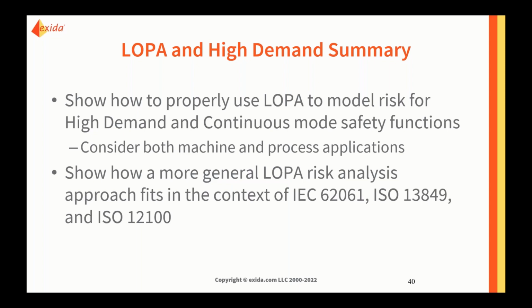For semi-quantitative LOPA, would I consider a basic process control system initiating event frequency of once a year being a high demand on a SIF, assuming that that is the SIF demand rate? Exactly once a year, that's the cutoff. I do not remember in the standard whether it's a greater than or equal to or a greater than sign, so I don't know which side the exactly once a year demand falls on, but I would check that in the standard. And then I've got one last question, and then we will tie things up.